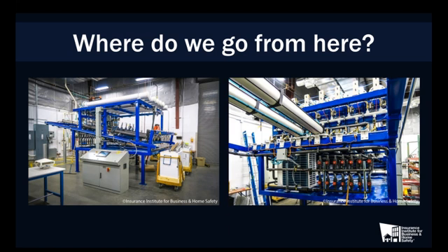It's about 3 years' worth of research and development, and it is designed to produce a very consistent ice stone in mass, so a capability of producing upwards of 1,000 of a given size per day. It's quite a sophisticated piece of equipment. We actually use diffused carbon dioxide gas that is injected essentially into water that's up in those big tanks at the top of the system. That helps us introduce a bubble structure and drop the density closer to what natural hail would be. And I'll show a couple of examples of the ice that this system produces.